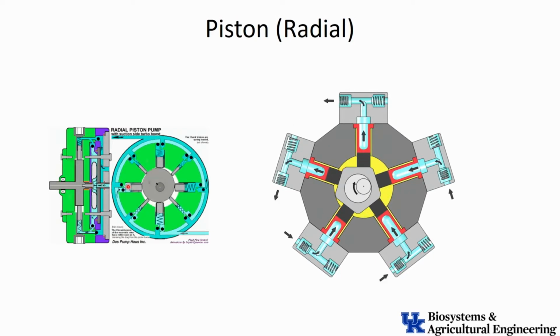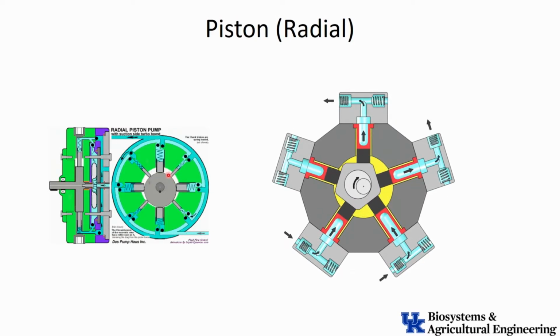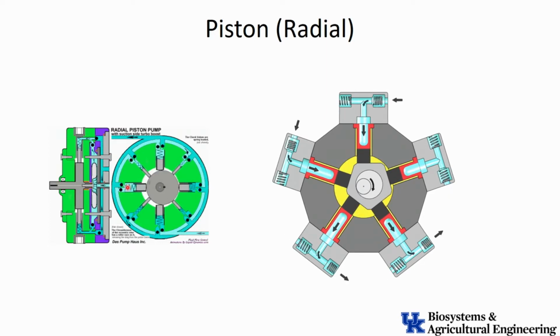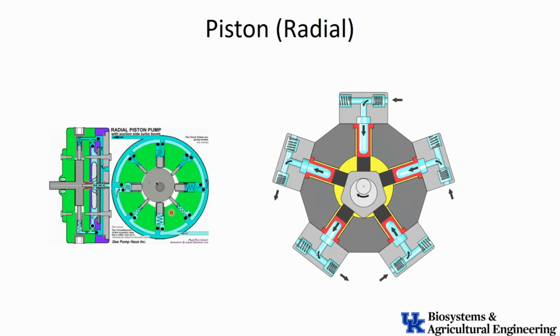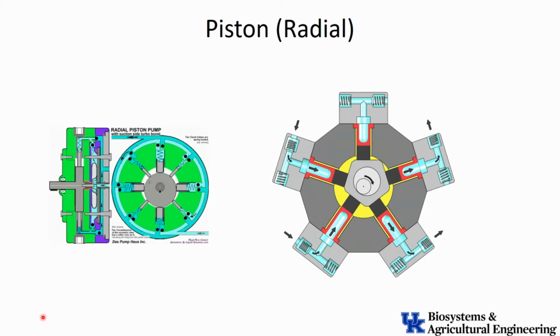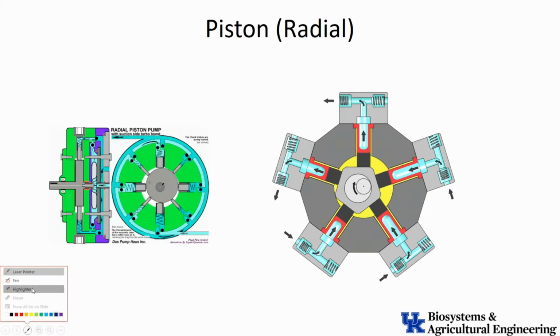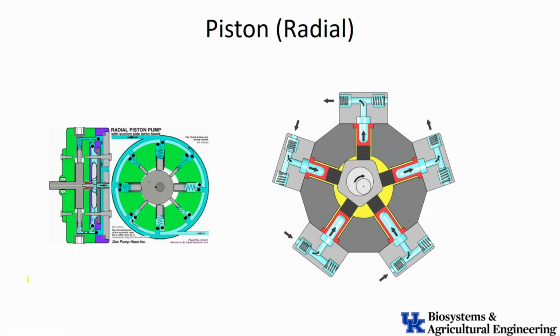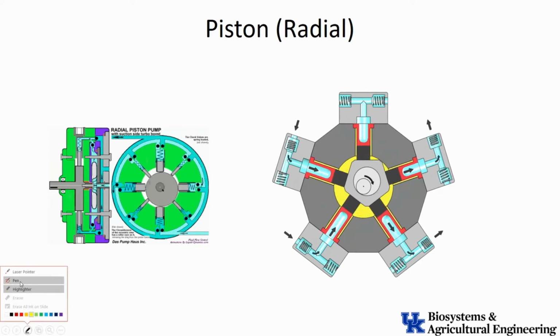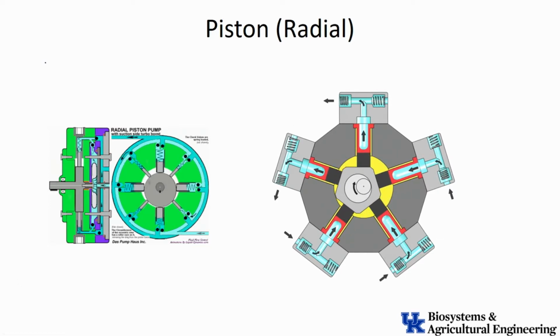It'll essentially hold the pistons out, lift them off of this camshaft, and the piston stays out and doesn't move in and out. Fluid through it. So the pump will essentially de-stroke itself. We talk about a pump de-stroking. The de-stroking is a pressure compensation.